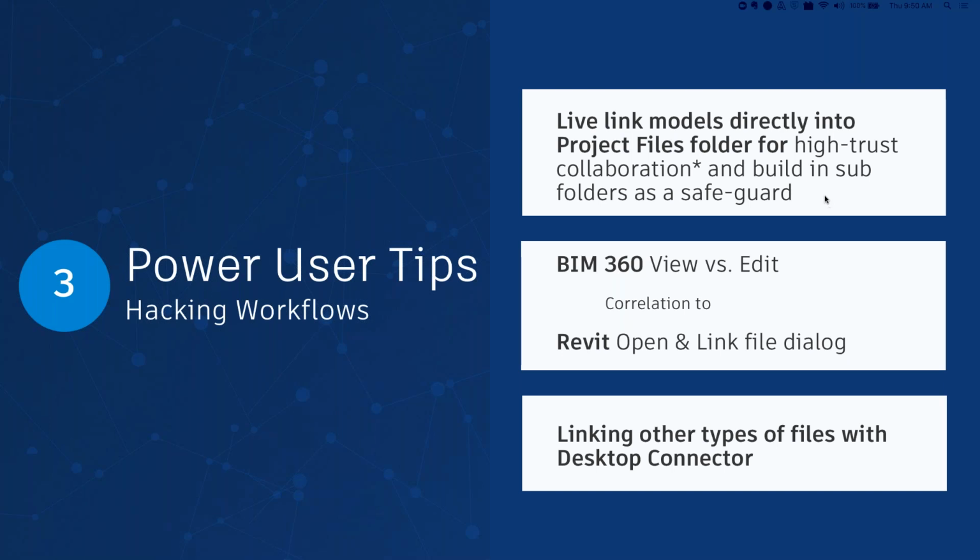So again, this is where subfolders can be really helpful, as opposed to having everybody in one pool, because you can give them view access, which sort of comes down to the next one there, where view versus edit is distinctly different here. You can give the structural engineers view access, which means they'll be able to link those architectural models. But if that same structural engineer goes to File Open and they try to browse the architect's folder, which they'll be able to go to the folder, they actually will not see any files to open because they only have view access. So those files are only going to show up in the links dialog in Revit. They're actually not going to show up in the File Open dialog.